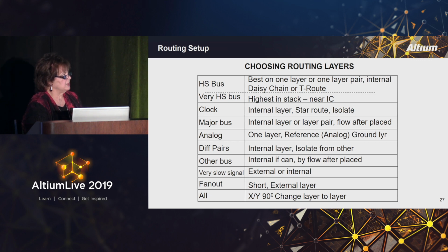Differential pairs go on internal layers and isolated from everything else. You can route differential pairs separately. I talk about differentials in a few minutes. It's preferred that you route them together, because if you route differential pairs next to each other, then you only have to worry about extra spacing on this side or on this side.